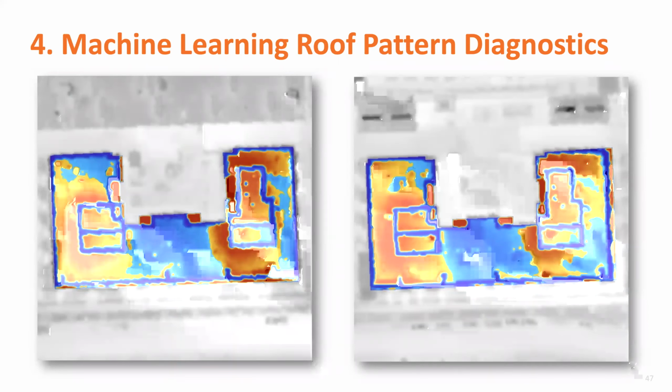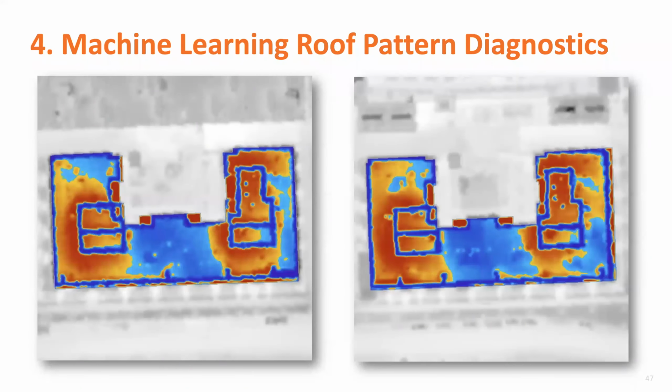These are two different buildings. It's not taken at two different times. Look at the area above it. They're completely different buildings. The city owns both of these. They were probably built using the exact same plan. And as you can see from their heat patterns, many of the same heat loss locations are occurring in both buildings. So the engineering that went into both of these buildings has been duplicated, and the energy that has been wasted is also being duplicated.